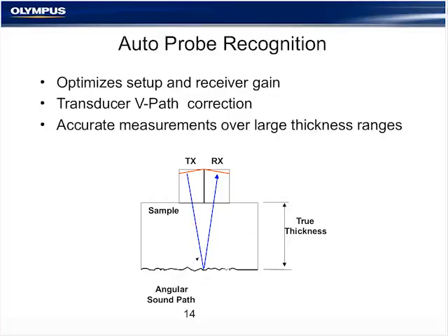What this does is it actually gives a type of focus to the sound. And for a backwall surface that's pitted or very rough and corroded, very uneven surface, this can actually help quite a bit with sensitivity when the sound reflects more focused off of a small pit and then is received back on the receive channel.